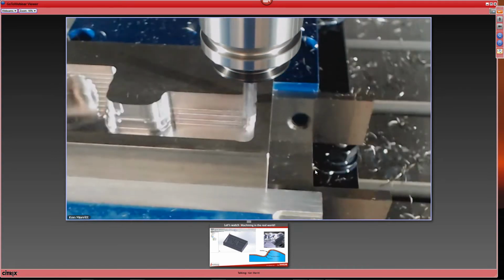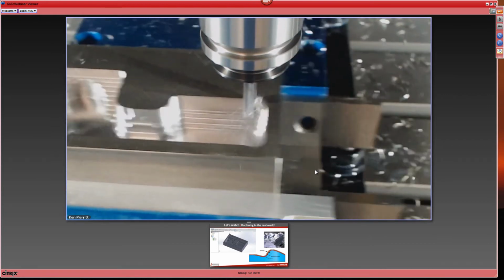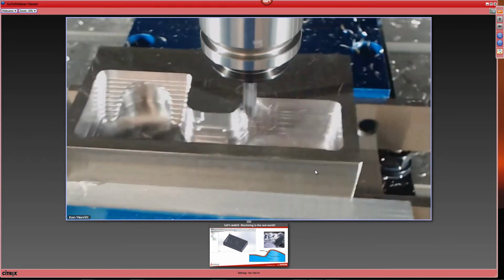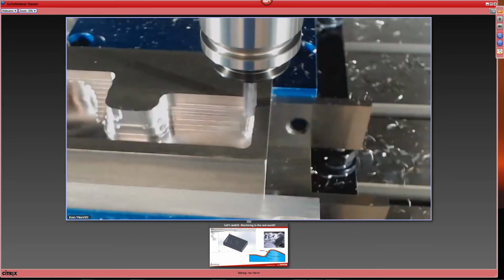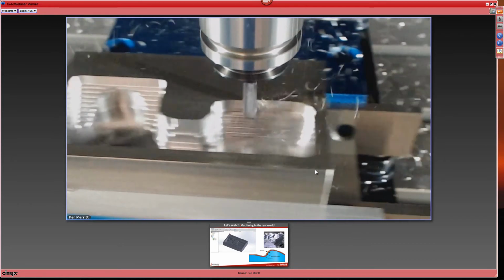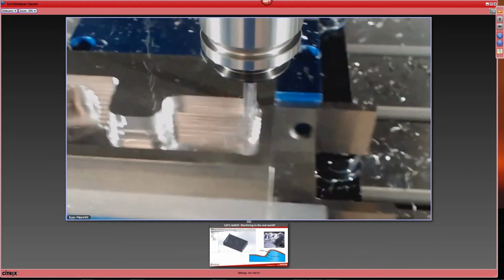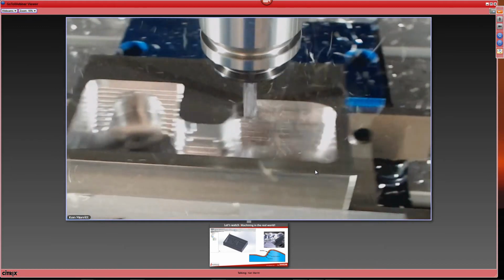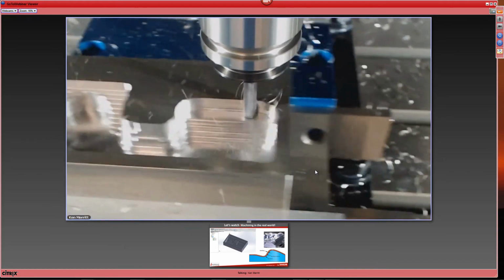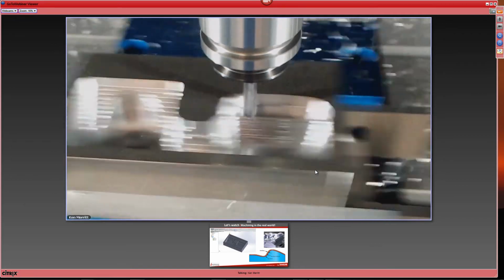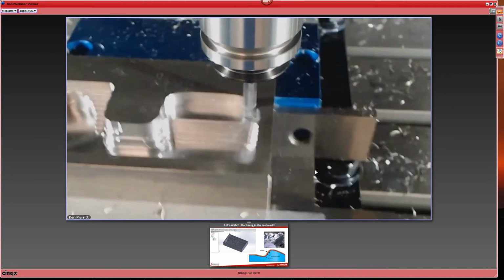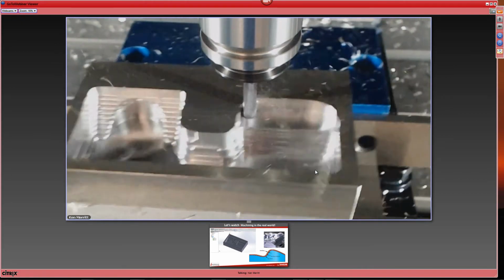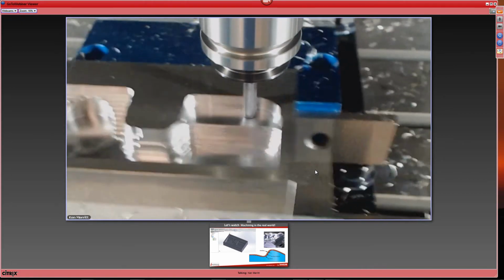Now, some people really don't understand all the depth of why that is important. When you have non-uniform staircasing in a roughing operation and you come back with your finishing tool, it's going to see an uneven loading and unloading of the tool. Therefore, you're going to get different flex against the surface, and it's going to create different grades of surface finish, if you will.